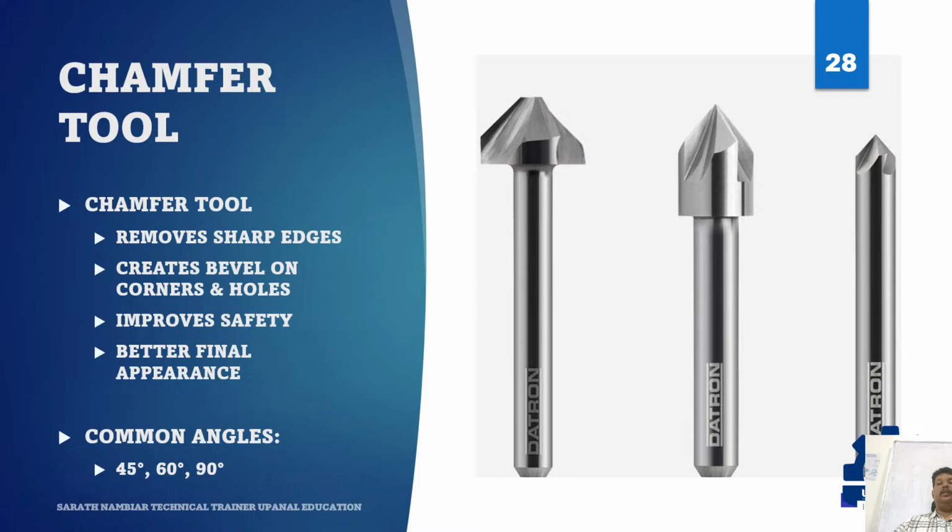A chamfer tool creates an angled edge, usually 45 degrees in many jobs, though other angles also exist. Where do we use it? Outside corners, pocket top edges, the mouth of drilled holes, and around the profiles. This improves safety, appearance, and sometimes assembly ease. Many beginners focus only on major machining and ignore final edge quality. But customers often notice edge quality immediately. So chamfering is not a decoration, it's a professional finishing discipline. When you see each component with clean broken edges, often a chamfer tool quietly did the finishing touch.